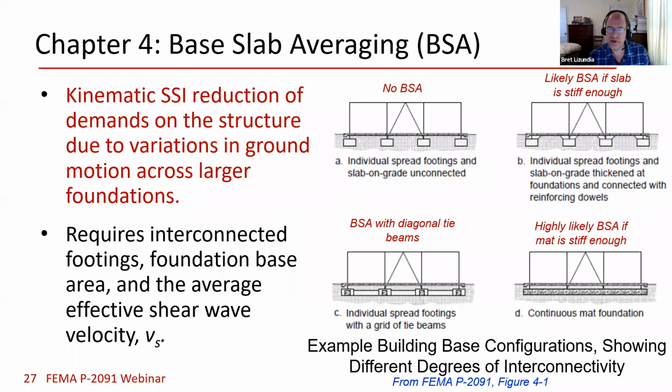So you may have a slab on grade building where the columns go down to spread footings maybe, and somebody may have intentionally put isolation joints to reduce cracking around those columns. They were deliberately not tying the slab to the columns.